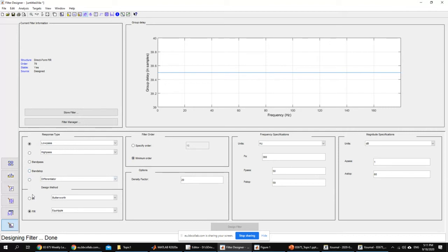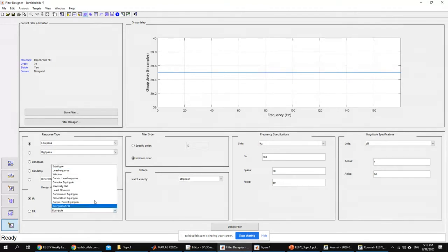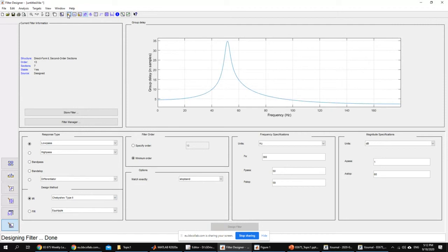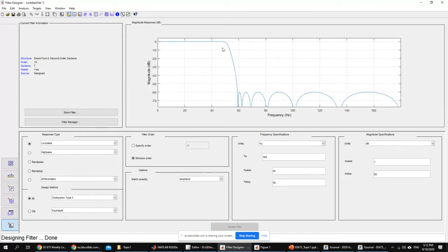Let's look at the IIR filters. And let's try, for example, any type. It's exactly the same specifications, and just design a filter. Okay, this is a filter. Looks very nice, actually. It's very flat here. It basically goes below the 60 decibels that we wanted at the point right before the point we wanted to cut off. It's fine.